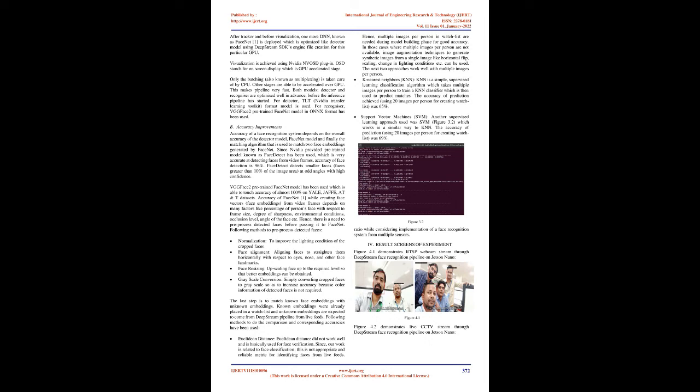Batching is an important step because GPU processes data in batches. Because of this reason, powerful GPUs are made with abundance of CUDA cores. Nvidia Jetson Nano has been used, which is having 128 CUDA cores. For best performance and as recommended, batch size is kept equal to the number of IP cameras attached to the device. In our case, batch size of 4 has been used. DeepStream batching process, also known as multiplexing, takes care of which face is detected from which frame and which frame belongs to which sensor. This is required so that alerts can be generated properly.